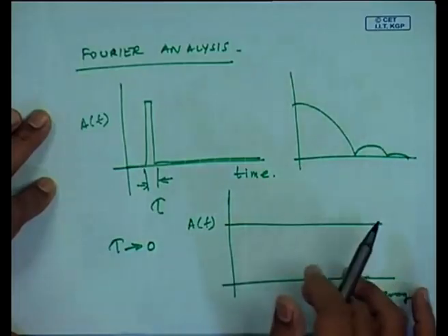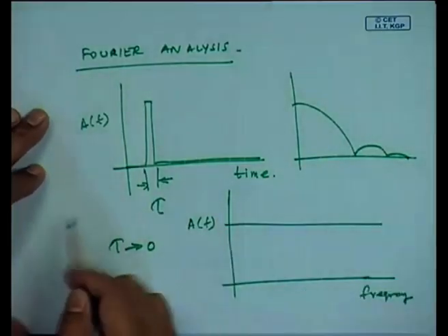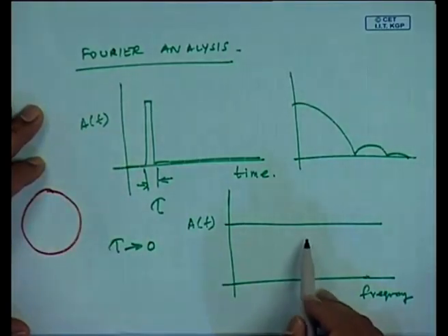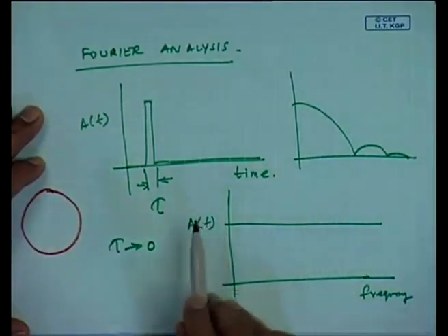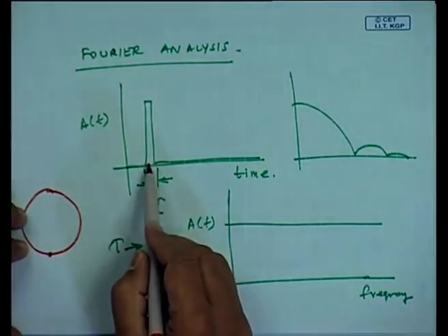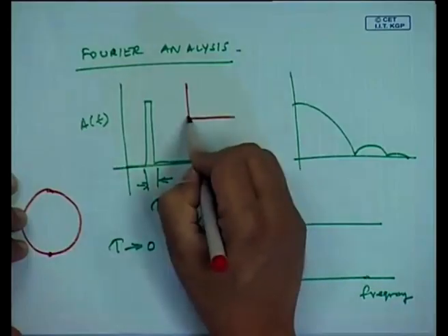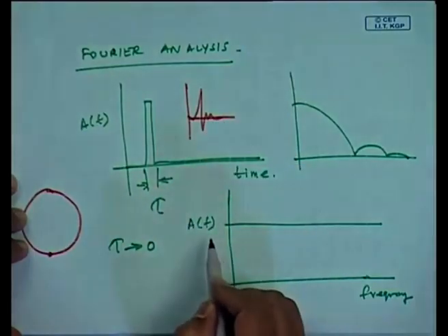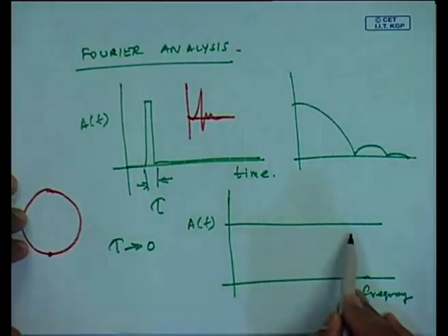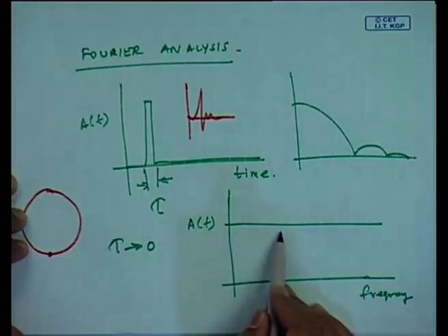So, now if I go back to the example of my rolling element bearing, the bearing is getting excited because of a small defect, which looks something like this or something like this, almost close to an excitation where all frequencies are present.